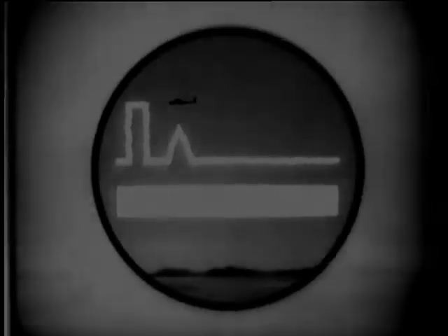So much for measuring azimuth and elevation. You'll remember that to measure range, you need only a single pip, A-scope, and the distance from the pip to the main bang represents the range of the target. As the target approaches your set, its pip approaches the main bang. The baseline or sweep, as we've said before, represents the full range of your set.